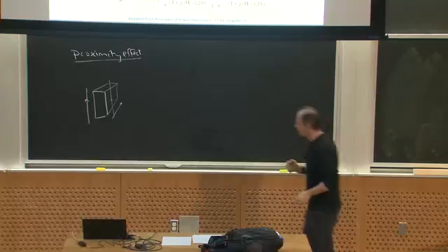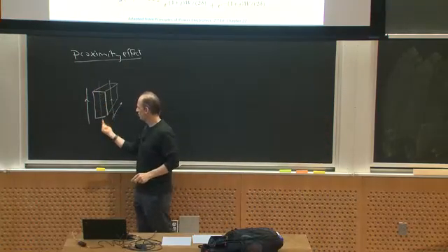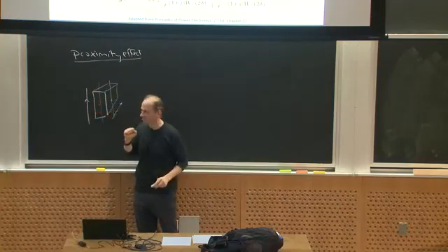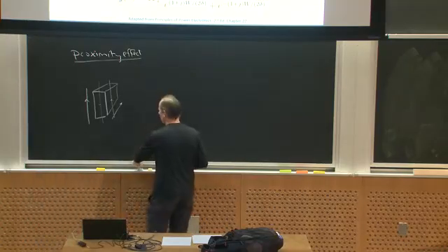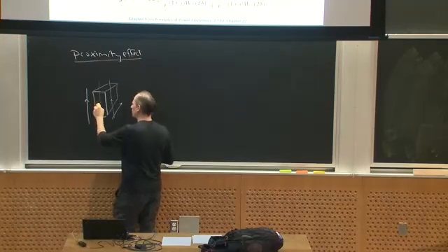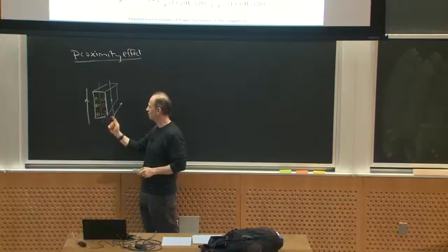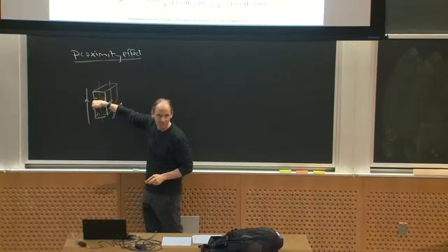Well, what should I expect? I'm trying to punch H field through the conductor, and that's going to generate some eddy current trying to reject the flux from the center. So it's going to generate an eddy current that goes in on this surface and comes out on this surface. Why? Because if this is an AC field, the dB/dt generates these circulating currents inside the conductor that try to reject the field from the center.